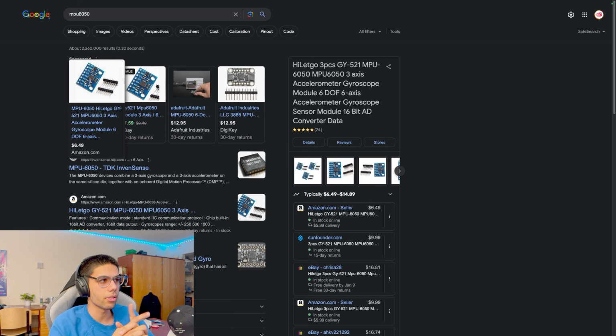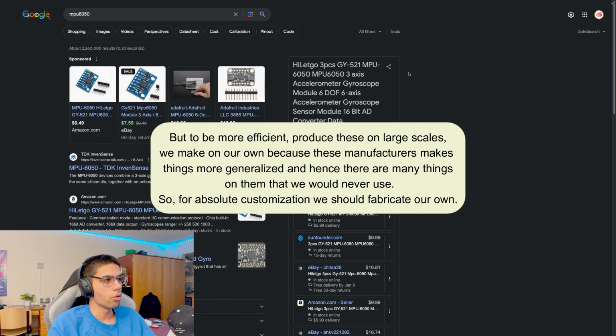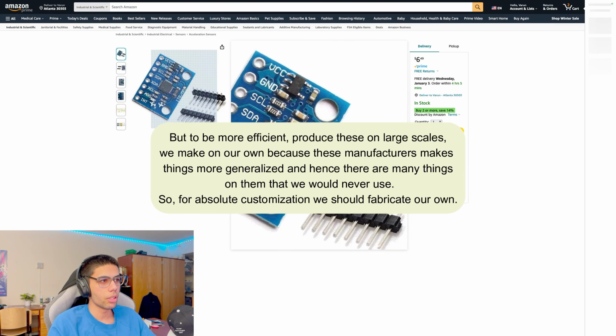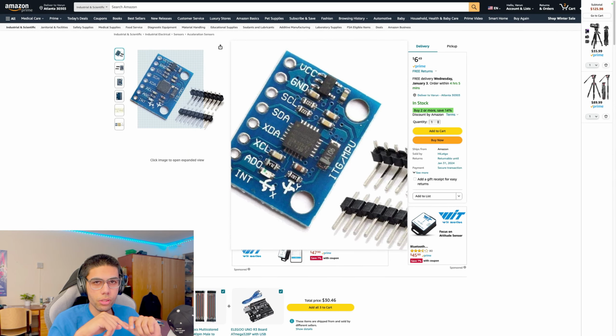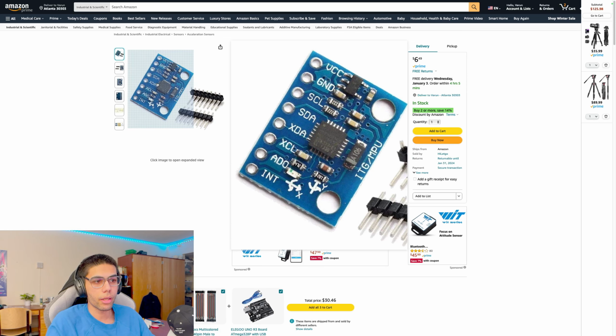Yeah, the entire board, because there's a lot of pre-processing on the raw signal that is implemented on that board. If we are not going to use that board, we have to do it all by ourselves. So to be quick and to save a lot of hard work, we're just going to use that. If you can open that to see what the dimensions are and how the pins are arranged, you can make your own library inside Eagle by putting in all of this information.